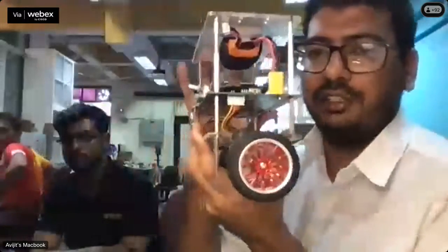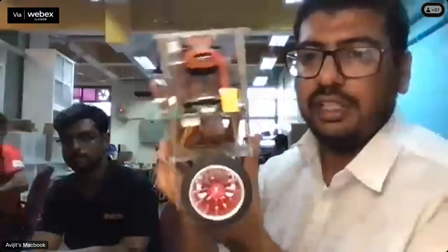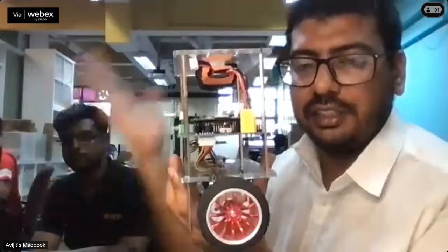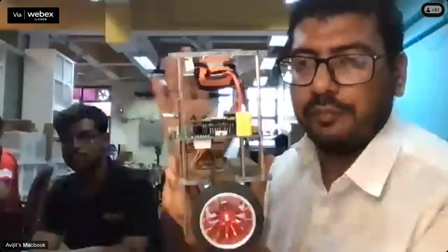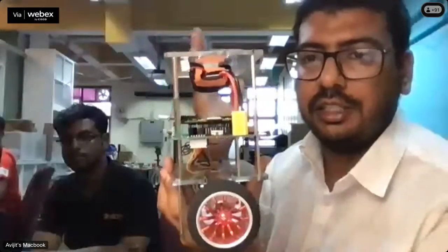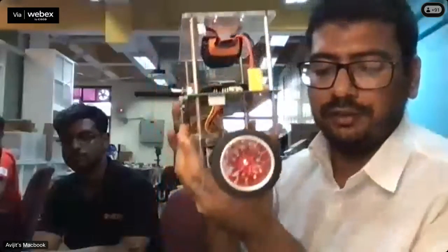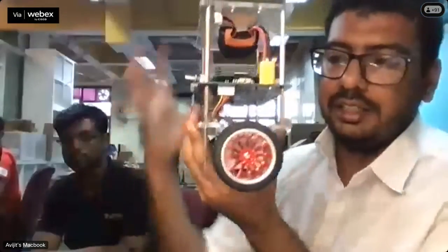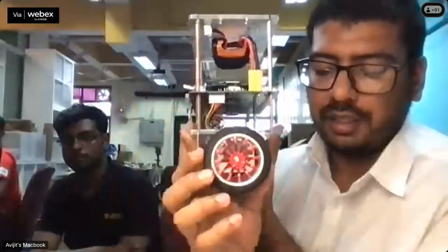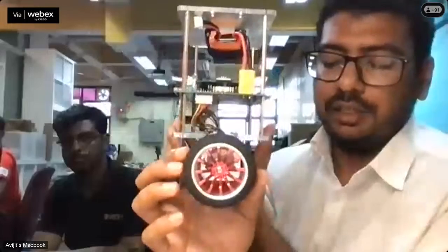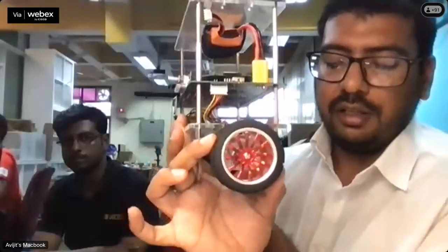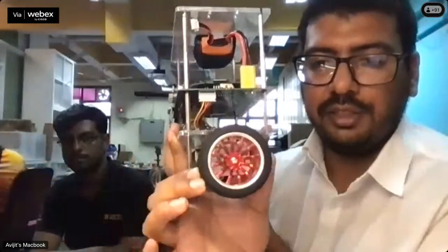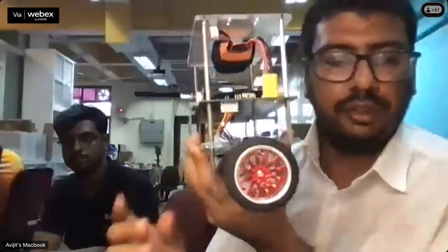Falling is an action; there's velocity in it. So we also want control over the rate of change of theta c, that is the rate of change of falling of the robot. That is called theta c dot, the time derivative. Same thing for the wheel. In this system, the wheel and the rest of the system are two separate parts, joined with each other through a motor. So we also want to control the angle of the wheel, called theta w, and the rate of change of angle of the wheel, called theta w dot. Is that clear?